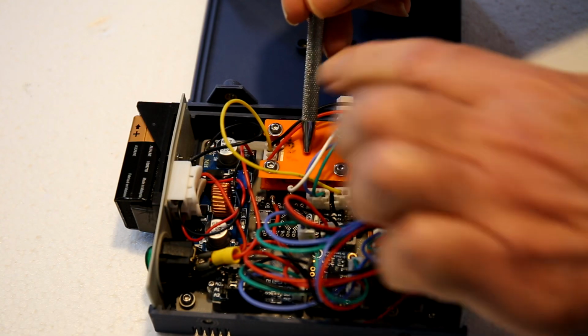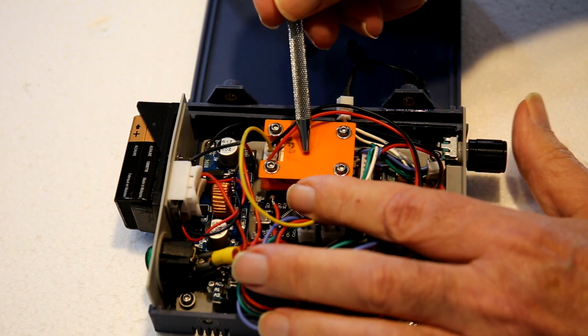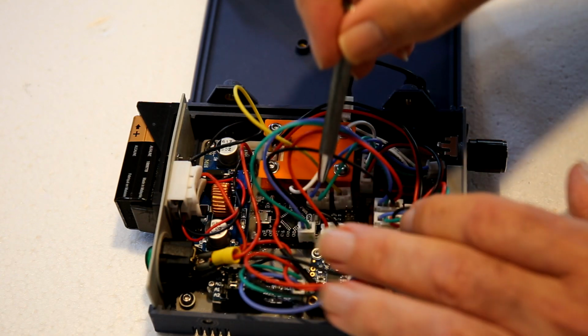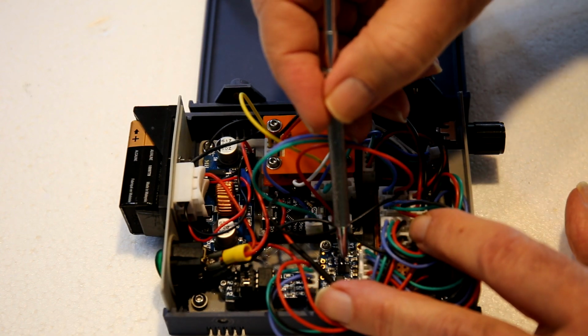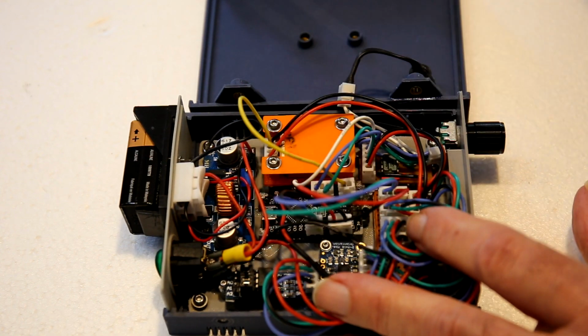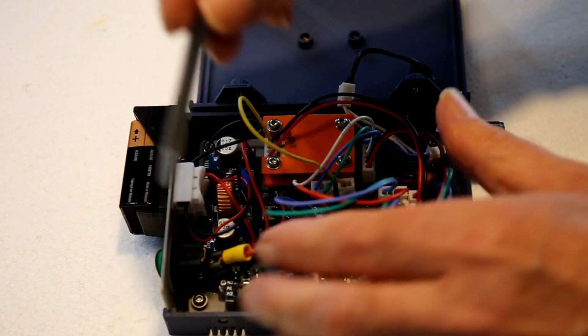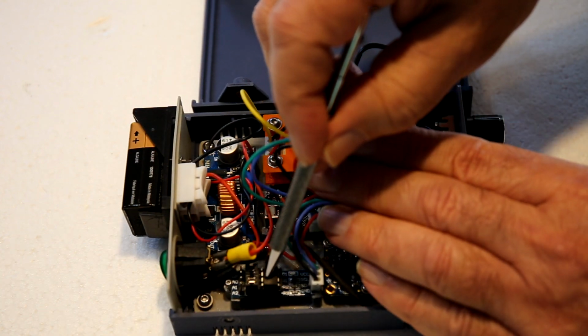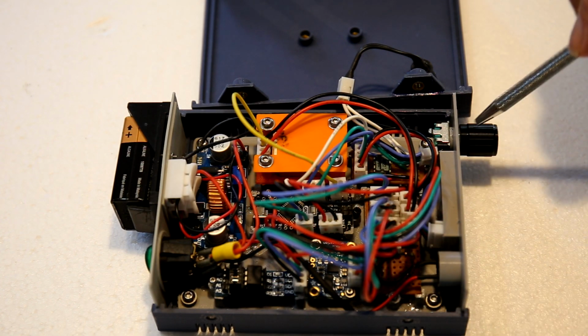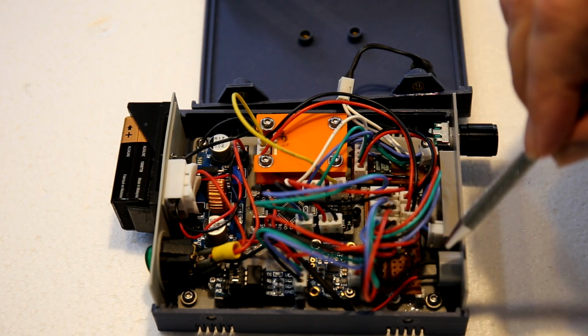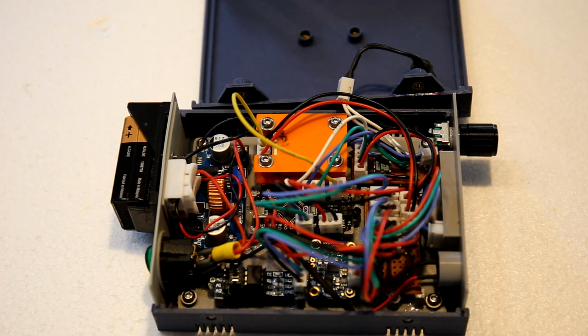The GPS module determines where the astrocompass is located on Earth and what time it is. The BNO055 provides information about the heading and pitch, the orientation of the compass. The EEPROM stores the catalog of celestial objects. The OLED display, the encoder, the push-button switch, and the piezoelectric speaker collectively make up the user interface.